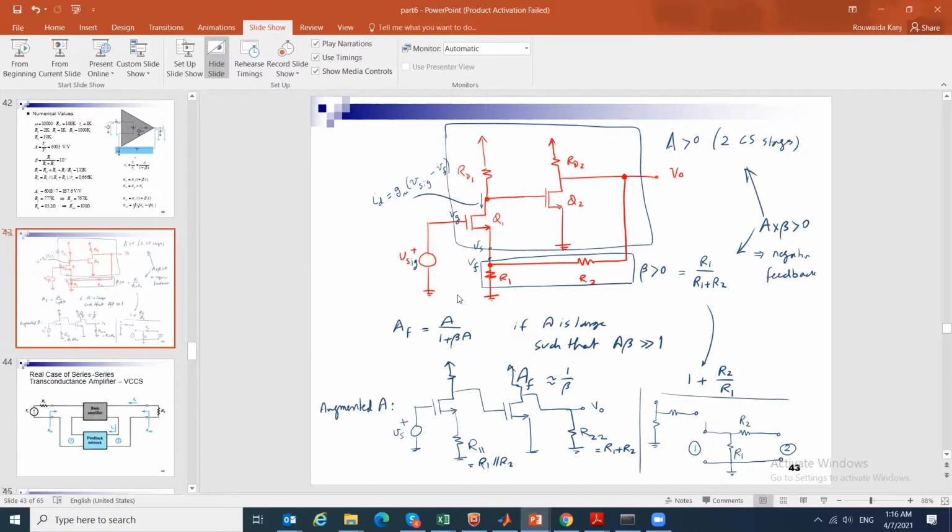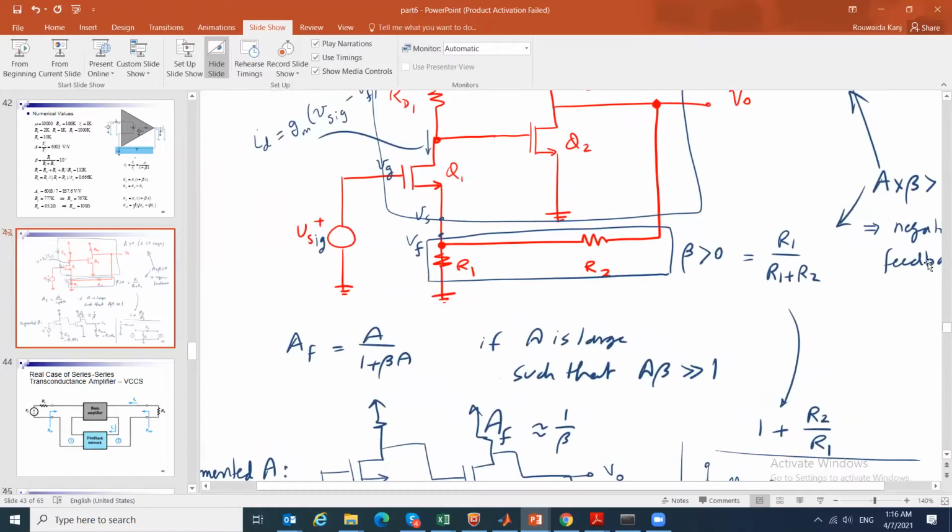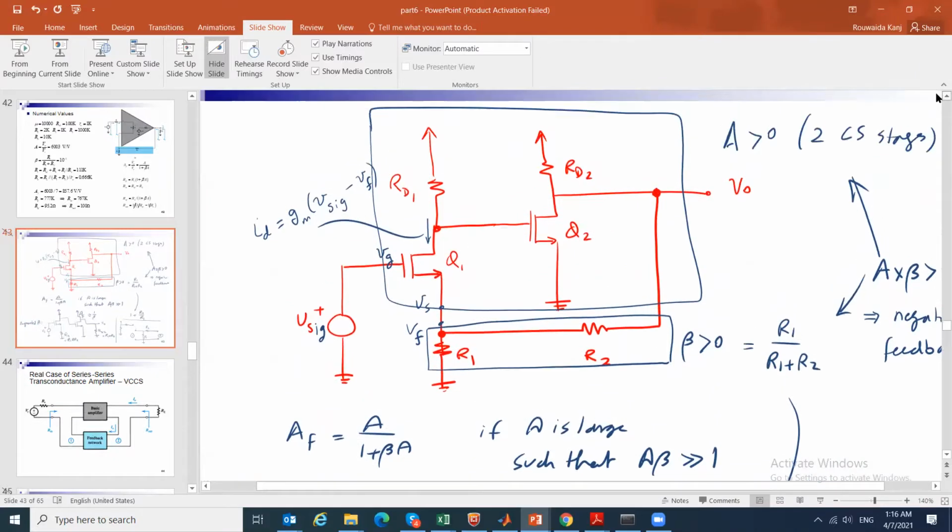So the main circuit that we are studying comprises a common source amplifier and another common source amplifier from the gate to the drain. And the last stage, we take a feedback via a voltage divider resistance from here to here and plug it in at the source node, such that if you look here, Vsig and Vgs and Vf form a loop, so it is plugged in series.